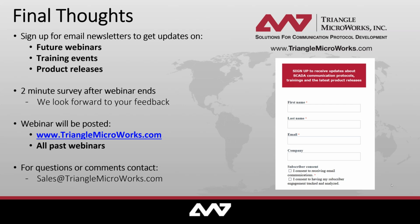So more of a general question that we did receive, and again, Jackson or Matt, either one of you can take this. What is the exact role of SCL Navigator, and can this also be done in Test Suite Pro? Matt, go ahead. So SCL Navigator works directly on the SCL files, your ICDs, CIDs, IIDs, SCDs, whatever. You can add report control blocks, you can add data sets, make modifications to communication sections.